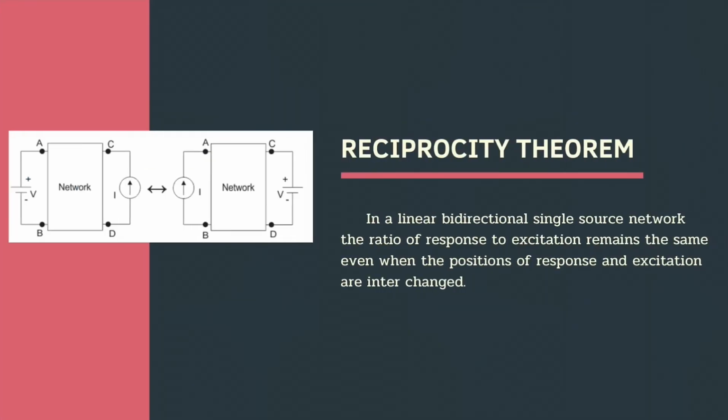And next we will talk about the reciprocity theorem. In a linear bidirectional single source network, the ratio of response to excitation remains the same even when the positions of the response and excitation are interchanged.